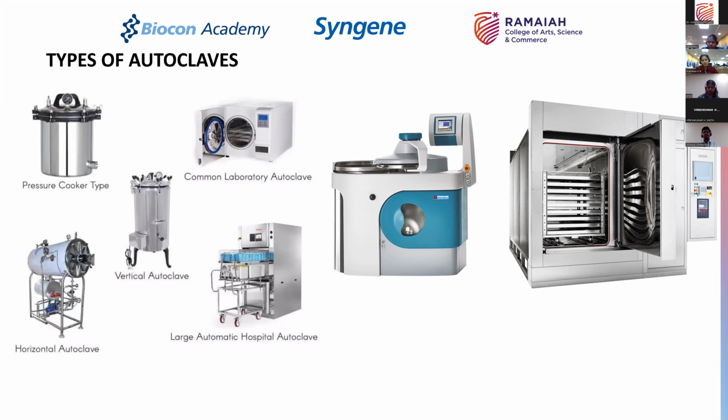Because if you have to worry about the level of the water, the effective space within the chamber again would go down if you had to have a large chamber like this, and if you had to generate a water system. Now, it is not an uncommon practice that sometimes you also have a steam generator provided by the autoclave supplier as an accessory to this autoclave, but it would be a separate equipment where you maintain the water level, and then you heat up, you generate the steam and inject it into the system.